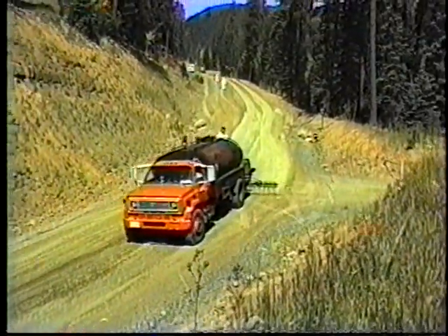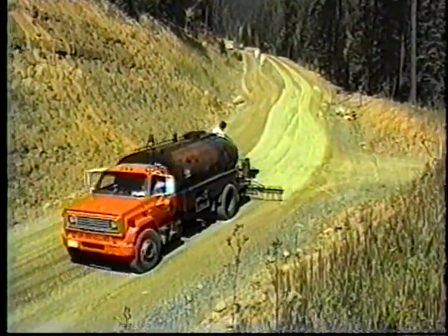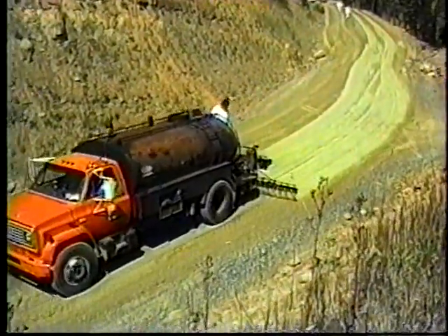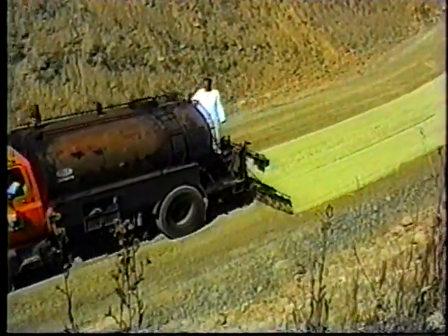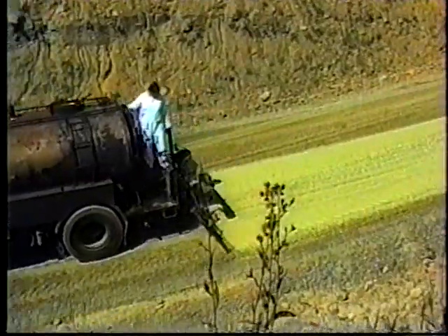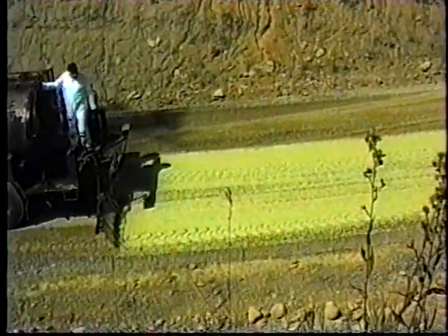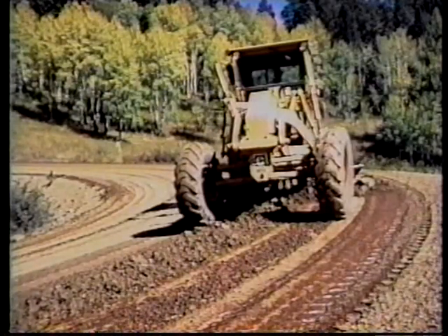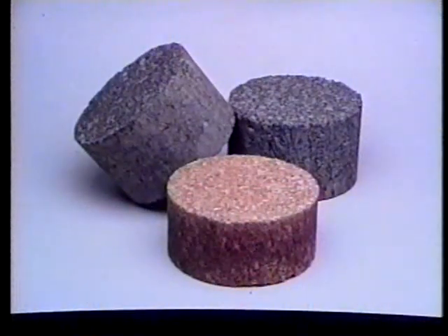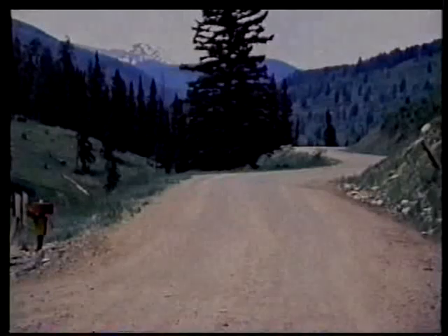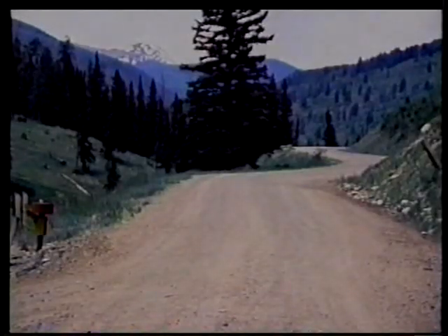As an immediate remedial measure, road oil was applied to the primary road, providing dust control and erosion control during the period of years until final cleanup measures could be implemented. Use of a non-petroleum binder kept all options open for final disposal or treatment of the contaminated aggregate. Road oil mix designs are being evaluated as options for construction of permanent pavements that will be placed to encapsulate the contaminated materials on adjacent roads included in the project.